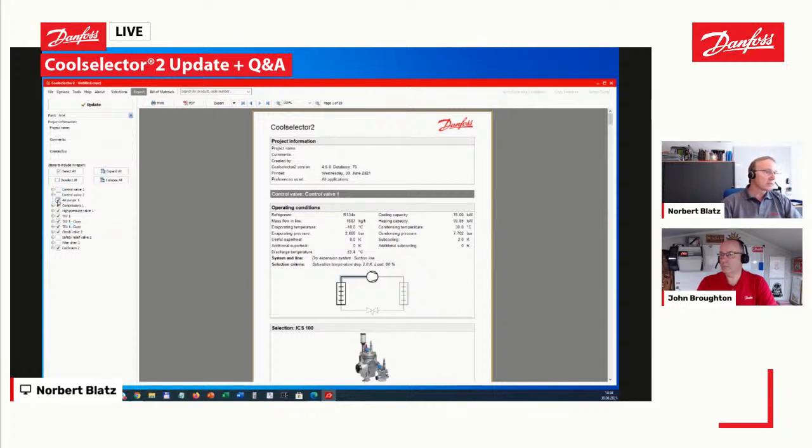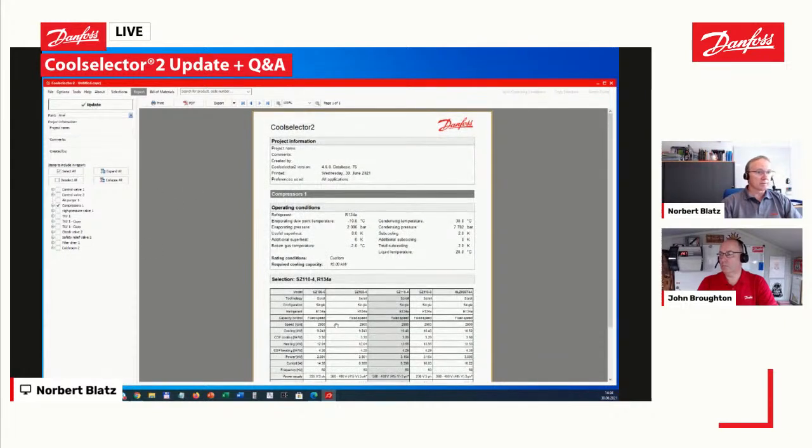Let me just remove what is not needed for this one. Update. So I have only the compressor. And if I open the dialog, you can see code number is default and the compressor type, but then you can define what else shall be part of the report, as well as the standard condition polynomials, or the polynomials based on your input conditions.